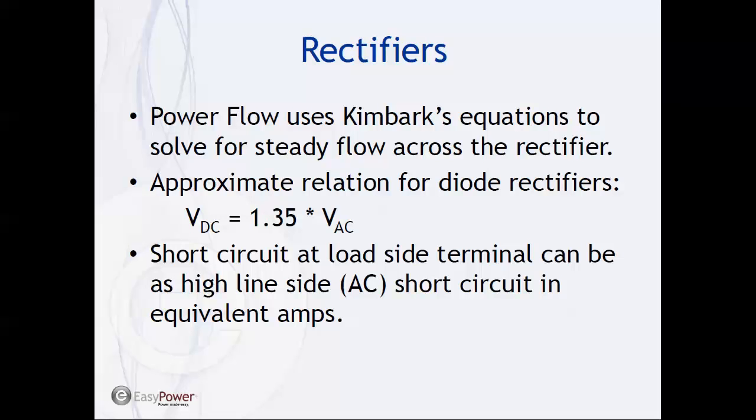For short circuits at the load side, for diode rectifiers, we can get currents that are equivalent to AC side faults. For IGBT types or thyristor types of rectifiers, it may be slightly different, so it's best to check with the manufacturer so that you can enter it in the rectifier dialog.